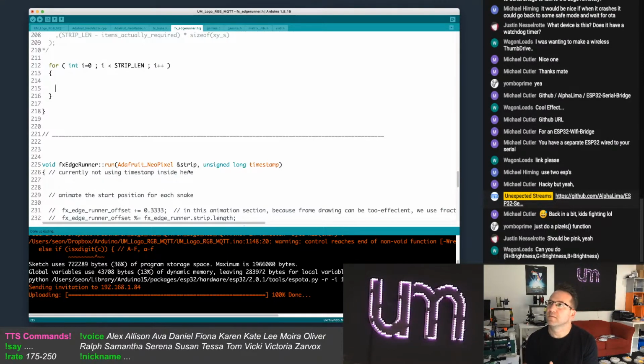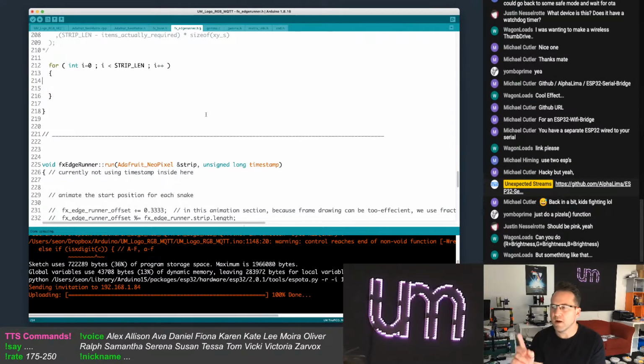How do I explain it? If you're doing the pink, for instance, which has a very small green component, and you're alphaing them down, then your green's going to run out first, which means the pink, as it fades, turns into a different color because it doesn't have the green component. Each one should be fading down a percentage of the whole. It's a little messy, and I want to start using gamma correction as well on these to get nicer colors, but I just haven't got around to that yet.